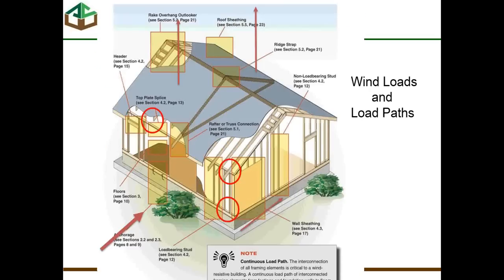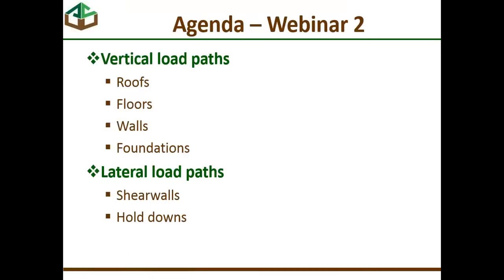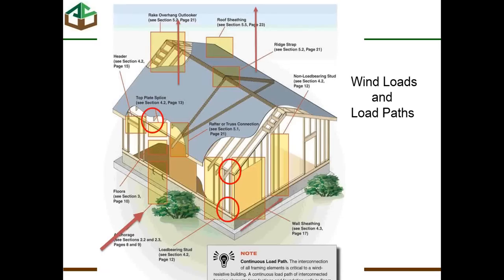I think we saw this graphic last week too. So you see several areas where wind is impacting the building. So you see, hopefully from my pointer, the direction of the wind assumed in this little graphic, applying loads that create uplift on the building roof and the building frame, and lateral load along the foundation. So you see this red arrow here along the right side suggesting a shear load along that wall.